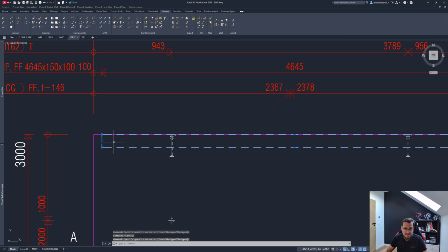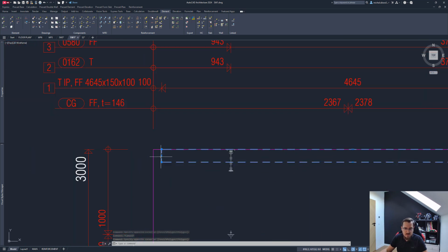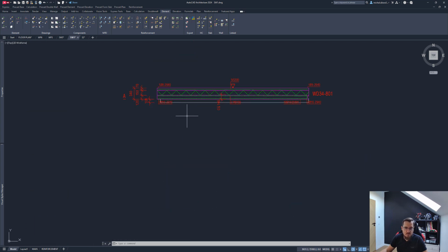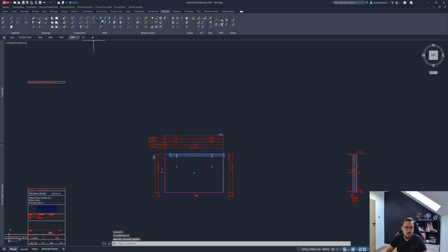Of course, we can edit that panel thickening here. We can move this line here slightly, and we will then edit the geometry of that panel thickening. So we can do that. I can go ahead and make that shorter, but I need to regenerate the geometry of the drawing as well. So I'll do that. And after that, I'll show you how we can add reinforcement to that now on the drawing, right? So it can be applied.